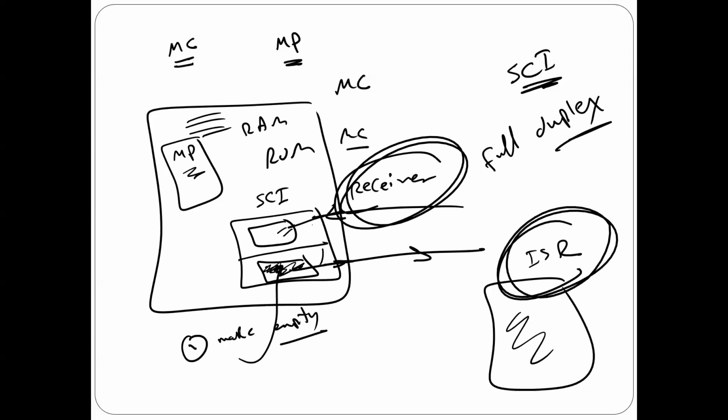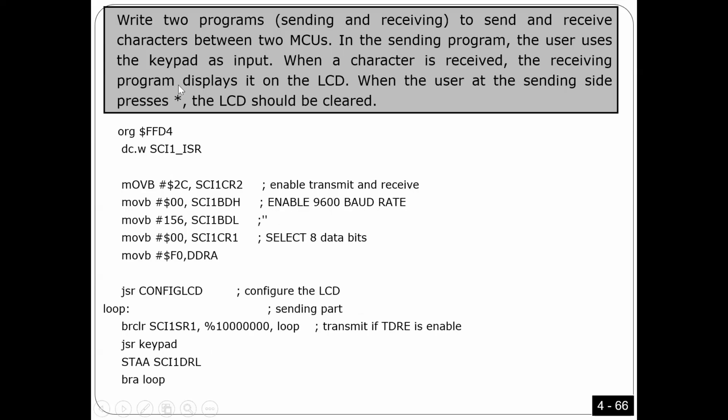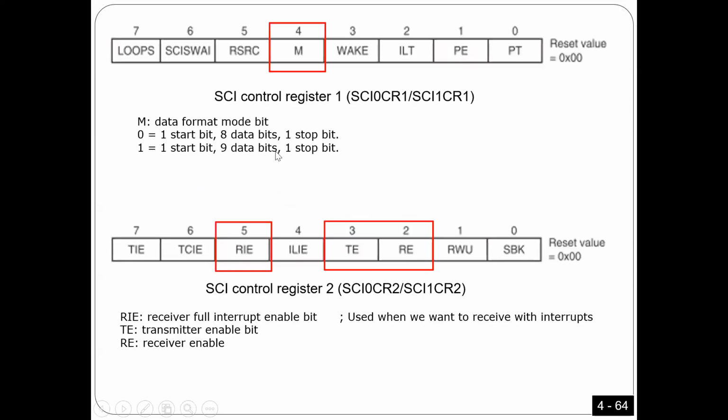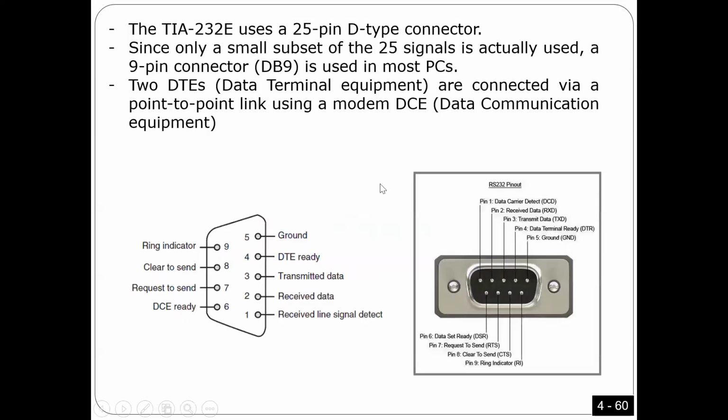Number three, for the transmission, you have to make sure the buffer is empty. Once it's empty, you just write the byte you want to transmit to the buffer. The hardware is going to take care of everything. You got what I'm saying? Very easy. As you will see right now, but before, I'm going to go through this again quickly.